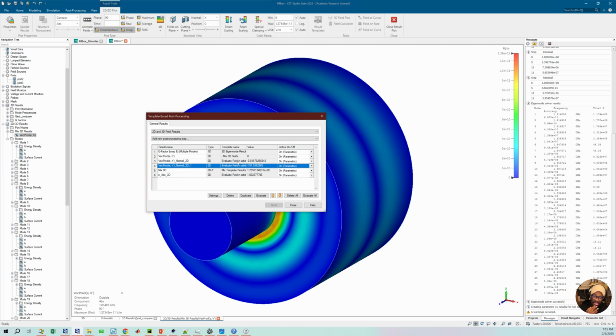Now, I also did a convergence study at some point for the complex frequency method of calculating it, and if I remember correctly, it never converged. It always fluctuated. That's the external quality factor. I could never really get it to be stable by making the mesh finer. So I think I left it. I only did one study, so it's not like I looked into it so much. But I haven't done it for this power method, and the power method has so many other steps to take.